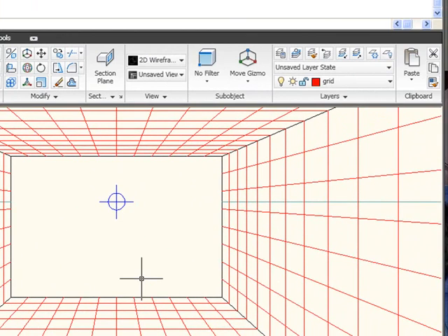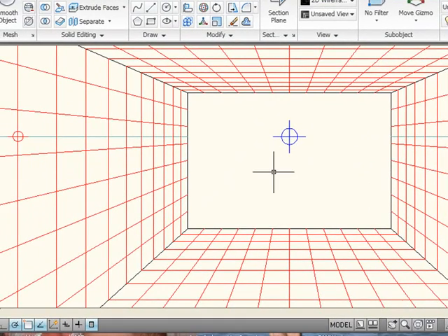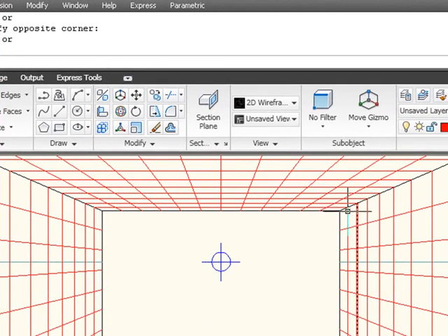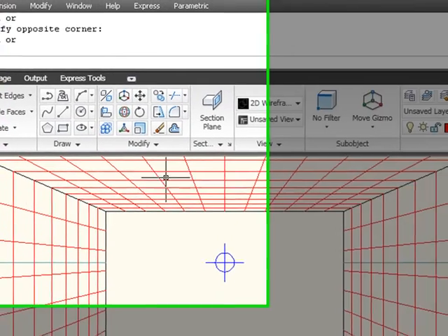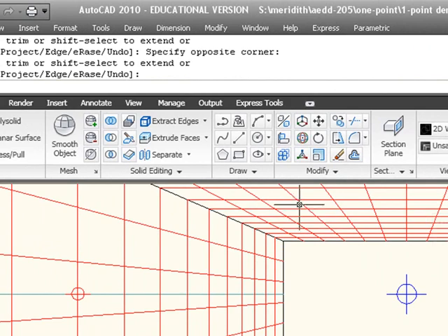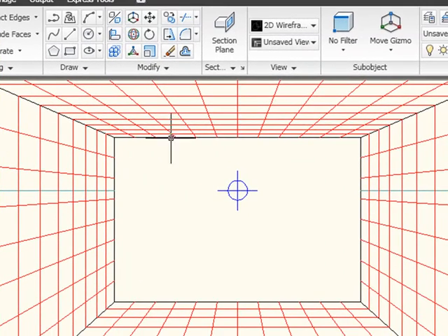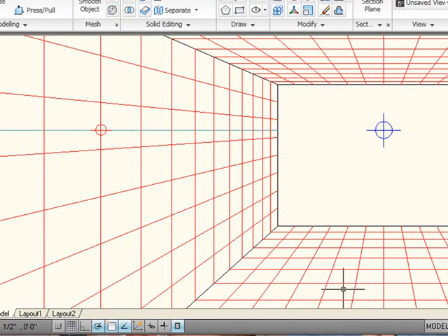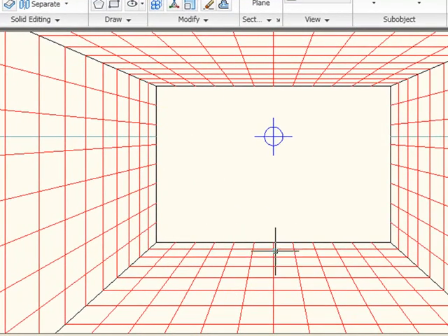But these types of grids, if you have a few of them laid out like this, can be really useful to do some quick drawings with. So I'd like you to create a grid like this one. You can either do it by hand or in AutoCAD. It is a good idea to set up some layers that allow you to print these lines at much lighter line weights for the grid and a slightly darker line weight for the outside edges of the building. That way when you start sketching, you can sketch over these lighter lines and still see what you're doing pretty well.